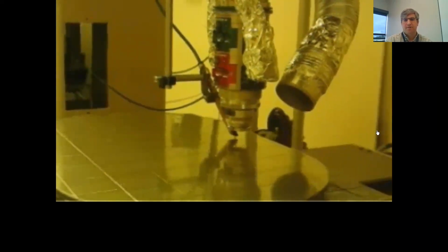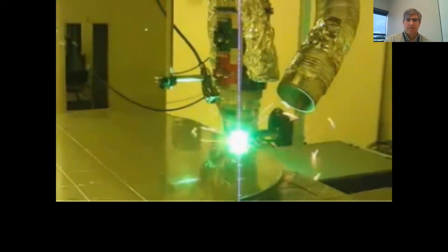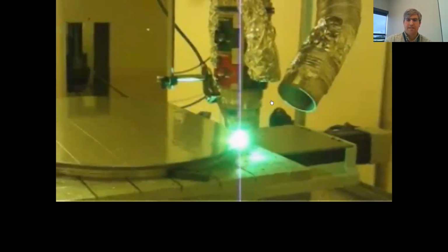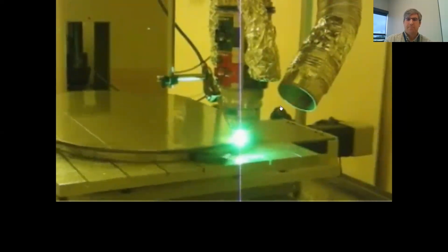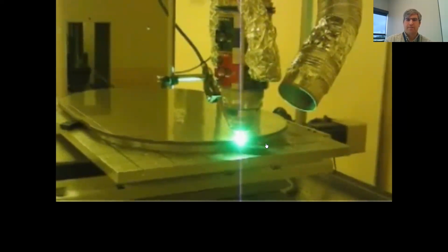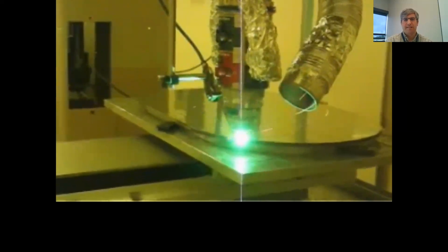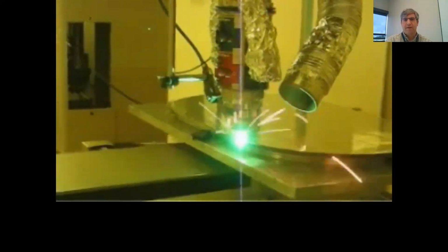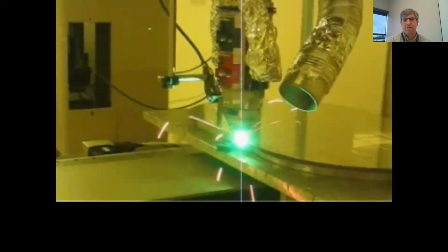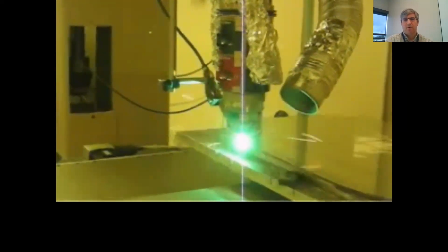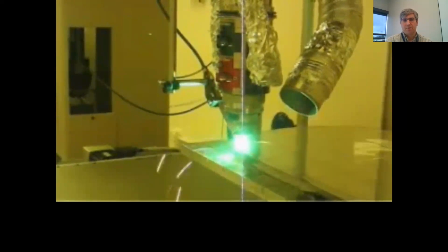You're using a laser as a heat source, and what we're seeing there is shielding gas, and this is an exhaust that's basically consuming all the fumes that come out of that. And so what you see in a laser welding process is a process that is much, much more rapid. This is done on an older CO2 system in a lab here at Penn State just to demonstrate welding of this component.